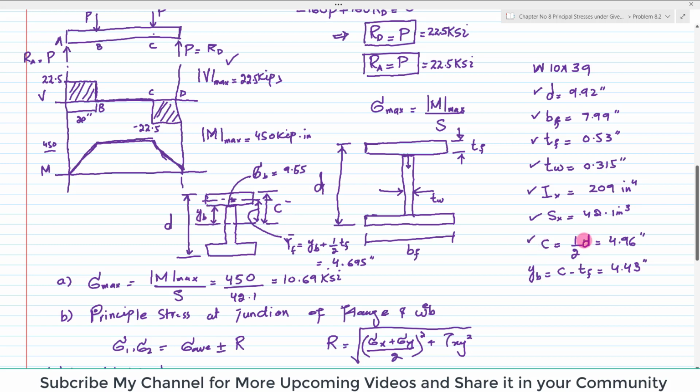C is equal to half of D, which is this one, and YB is equal to C minus the thickness of the flange. So if you subtract this thickness from this C, you will get this YB, clear, not this. This is YF, this is something else. So C minus this thickness will be YB, clear.